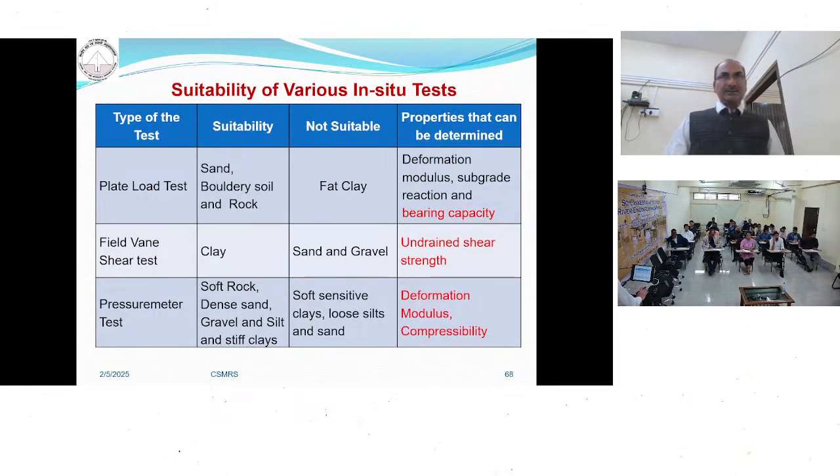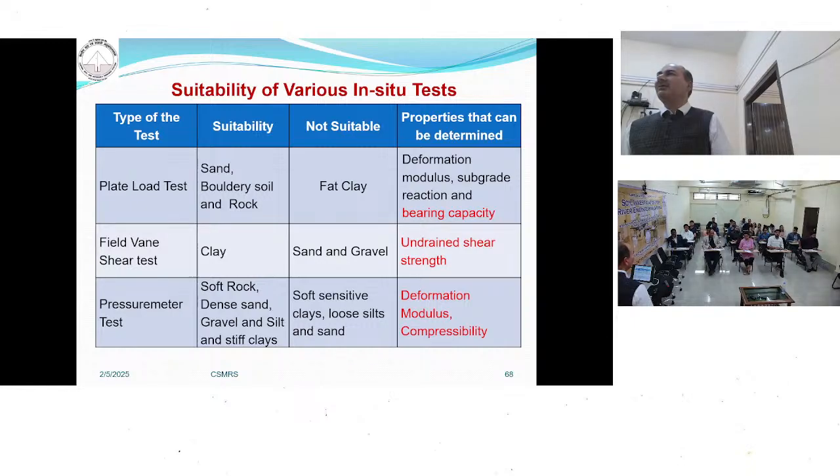Plate load test. The plate load test is suitable for sandy, gravelly or bouldery strata. It is not suitable for clay strata or fat clay. What does it give? You must have read about the plate load test. It gives the bearing capacity, settlement and deformation modulus.